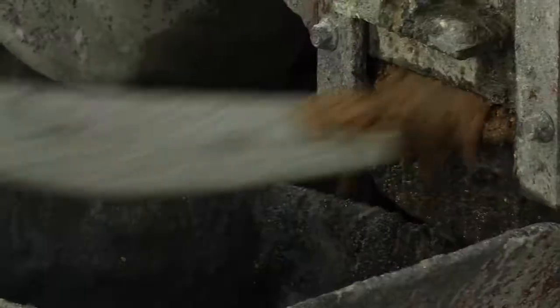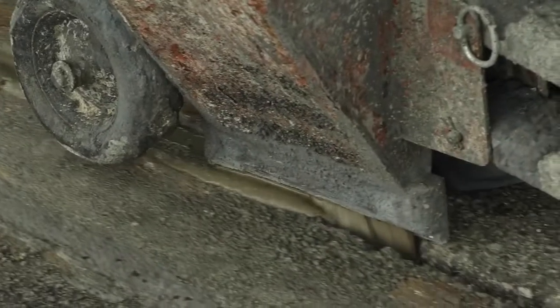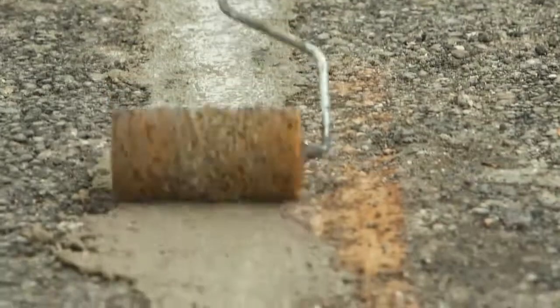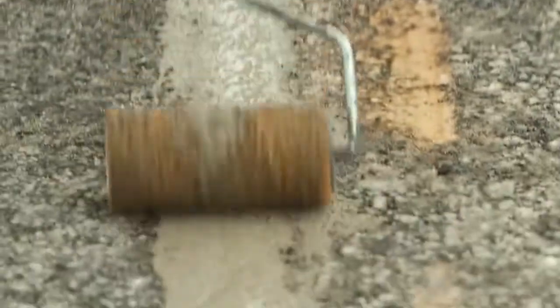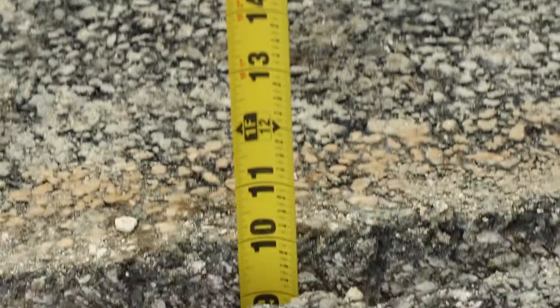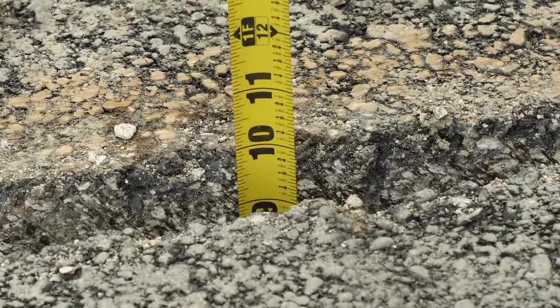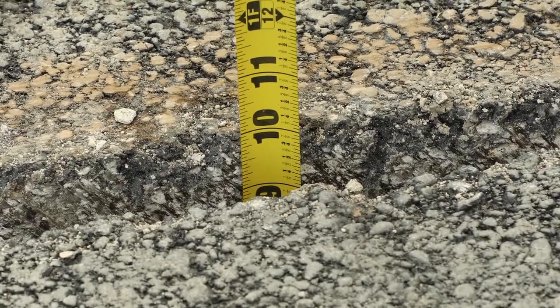2. Concrete slurry or thermosetting MMA resin. Concrete slurry or thermosetting MMA resin provides a more aesthetically appealing finish. They include special bonding agents that limit water migration in the trench. In some cases, the trench depth can be reduced with this method when compared to asphalt restoration.